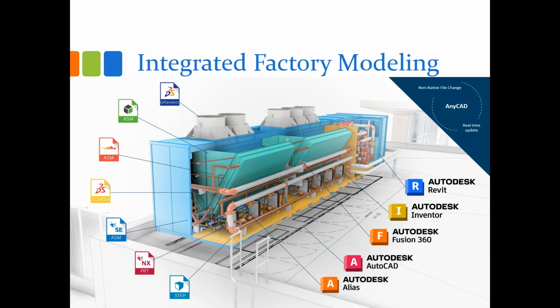Inside of Inventor, we can bring in Revit files, RVTs, any older Inventor files, IPTs, IAMs, and Fusion 360 files; we can link those through the Autodesk connector. AutoCAD files we can use as overlays, especially on the factory side, where we can use them as backdrops. Alias files, if we want to link in some surfaces. STEP files we can convert or maintain a link. So if we're getting an updated STEP file, we get it updated as well. CATIA products, SolidWorks products, solid assemblies, solid parts, all of those can be placed as live links.